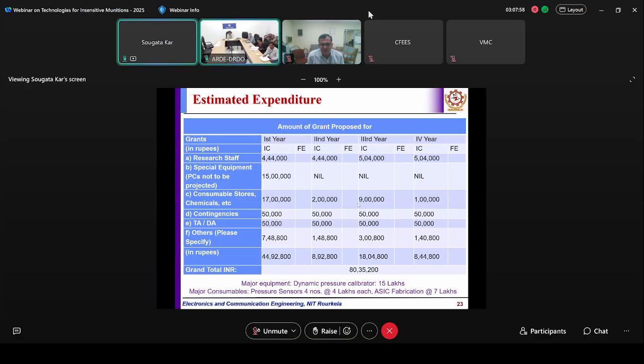Sir, you are already making a similar system for PXC. What is the difference between this and the proposed system? Sir, for the PXC, it is the gun chamber measurement where the pressure range is very high, 1000 megapascal. Sir, range is not a matter. All sensors have some standard, with an output of 5 volt, like most of the sensors we are using. The IEPE standard is there. It may be 50 psi, 1000 psi, or 1 lakh psi; it will always give a 5 volt output. So range is not a big issue here.